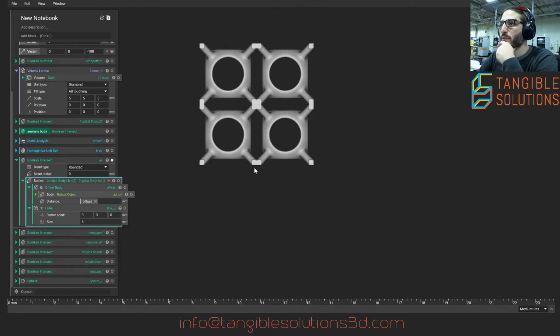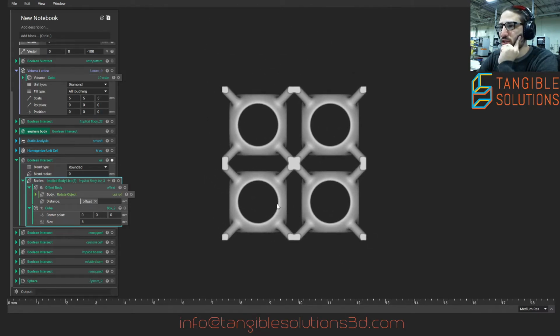It did give me the mechanical properties I want. When we look at a TPMS structure yielding plastically, it has a really cool stress-strain curve where it holds the load as the load is building up, and then it plastically fails, but only the first layer. Then it all smushes down on the next layer, and you'll see it start ramping up again, and then it'll plastically fail again. Usually that's tied to the periodicity of the structure.